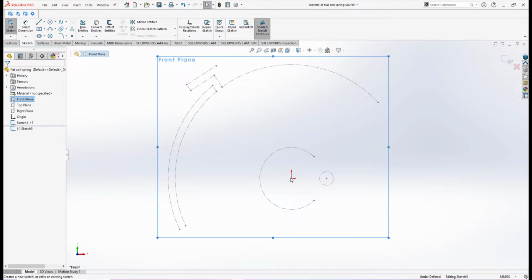To make the spiral curve, similar to my previous video where I did the curve driven pattern for the arms of the shaft, I used a helix. With a helix we have a curve and a spiral shape, but the helix has height and revolution.